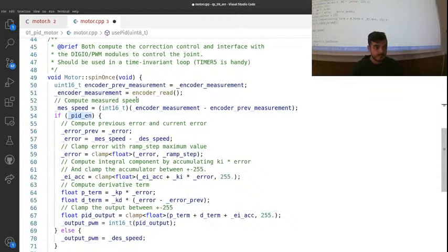These variables will then be read at interrupt time during spin once. In this way, you do not corrupt, because we have 16-bit numbers, and by setting aside, you don't have the case where you write an integer while it is being read. You know what I mean? You just write on your dashboard, and then there is another actor in your system that will read the dashboard.